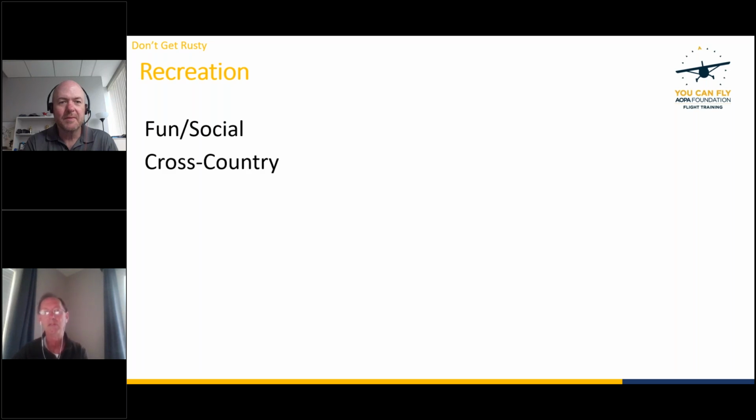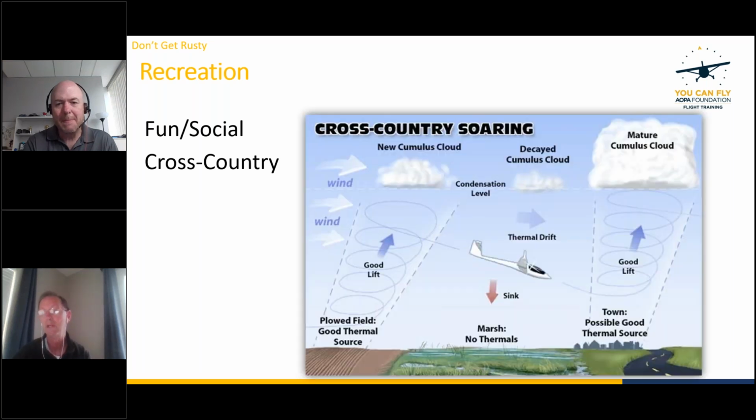It can also be relatively challenging. There's a part of the sport called cross-country flying, where basically you're trying to go somewhere and hopefully get back again using various sources of lift. So, for example, the thermal lift, where you climb under a thermal to get some altitude, you use that altitude to glide to the next source of thermal lift, you climb back up again, and you just repeat that process for hours on end. And you can literally fly hundreds of miles and come back home again, all just using the energy in the atmosphere. It really is amazing. You could also use ridge or wave to do the same thing, or convergence. Any of the sources of lift, anything that'll get you a little more altitude that you can exchange for distance.